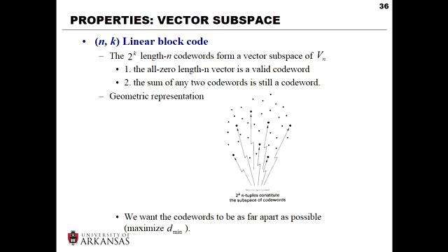So soft decoding is the optimal decoder. It will give us the best possible performance. And hard decoding will have some performance loss. But performing optimal decoding is not that easy, because it means that we need to search all the code words and find the one that has the minimum distance to the received information, right?